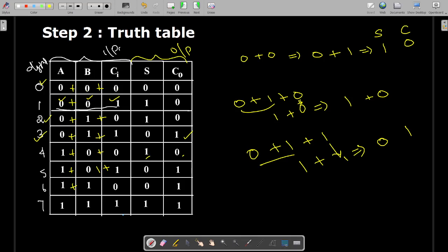And this 1 plus 1, you will get the sum as 1, along with that the carry is generated. Okay, so you have to then add this along with this. Actually we put it like this: 1 plus 1 plus 0. So 1 plus 1 is 10, right? So actually this is the sum, right? This is the carry, and this sum is to be added with this 0. So 0 plus 0 results in 0 only. Okay, so the final sum is anyhow 0, and this is your carry already generated.